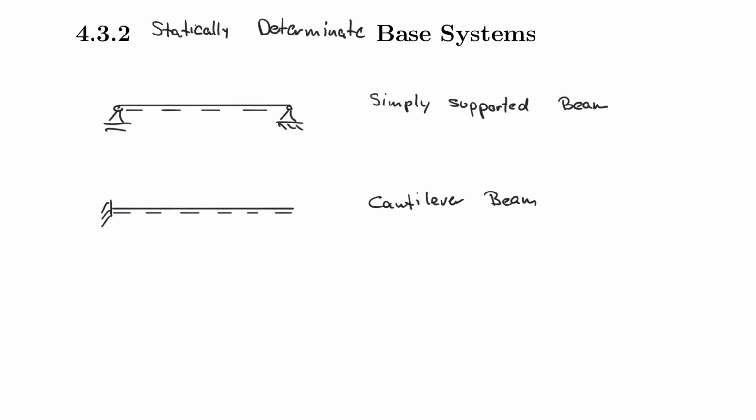And you probably understand now why this is called a simply supported beam, right? Because this is as simple a support as it gets without being a kinematic system and without being overstable. So we call that simply supported. And you also understand that these systems, of course, fulfill the 3 conditions: the sum of the forces in X, the sum of the forces in Y, and the sum of the moments. All of them are equal to 0.